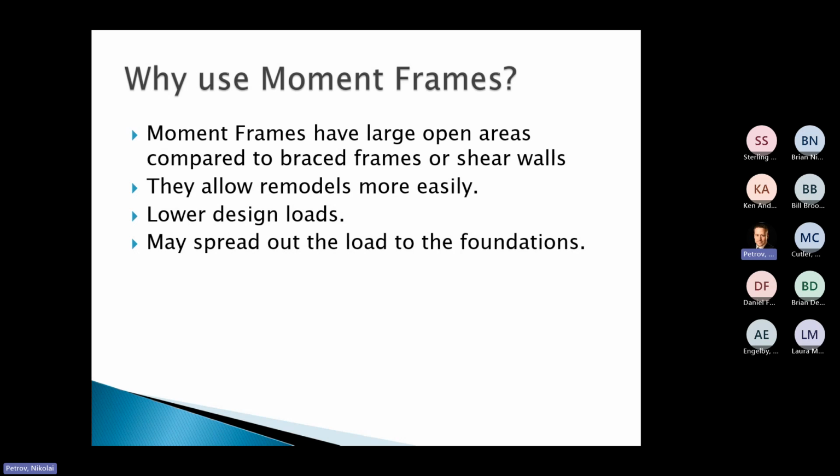That's one of the things we're always fighting on the engineering side when we have shear walls and brace frames. Where do we put them? Where do we hide them? Invariably, we'll have an architect who wants to give us a floor plan where there is no opportunity to put one in without making somebody angry or putting something in the way. Moment frames get out of that because you have larger columns, but still it's just a column. Architects are really good at working around columns, and they don't mind when columns end up in the middle of certain spaces.